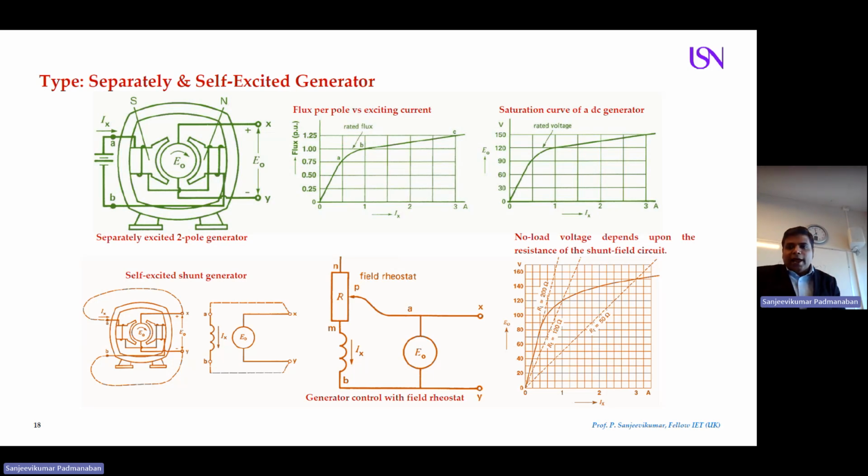Okay. I'm going to look at what happened at zero excitation current. At zero excitation current, my output voltage is 0. As I keep on increasing, you can have a look, it linearly increases, reaches more than 160 volt at greater than 3 ampere excitation current. If the resistance is 120 ohms, you can have a look, it starts at 0, current 0. As the current increases, it steeply increases. It reaches the maximum value of 160 volt at less than 2 ampere, say 1.2 ampere. For this resistor value, 50 ohms, I need 3.5 or 6 ampere.